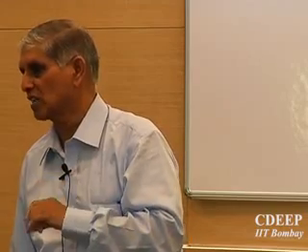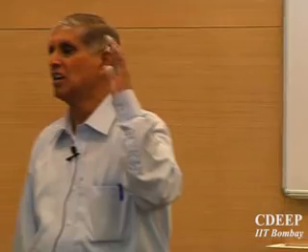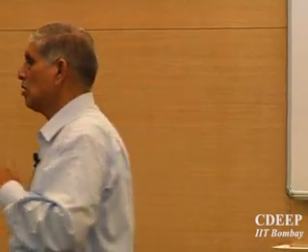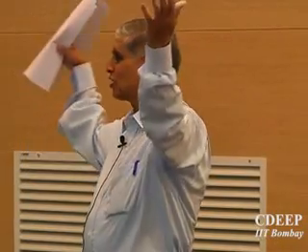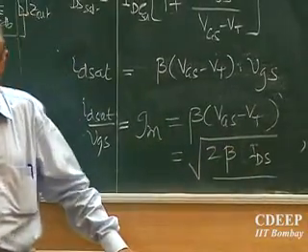Why intrinsic? No loads, no external circuit. Intrinsic gain of a transistor is GMR0, and if you increase GM, R0 goes down. If you increase R0, GM goes down. So the product does not change drastically as everyone thinks. Oh, I can make huge gains. Okay, it's not easy. The alternate method there should be, if I cannot change IDS, how can I increase GM?